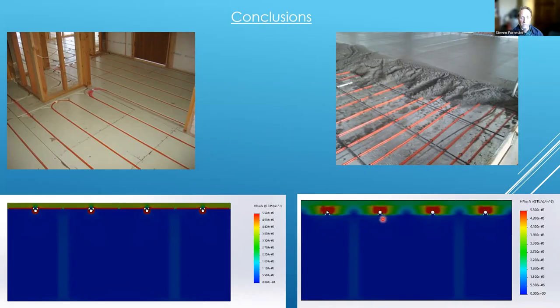So in the Front Range of Colorado here, when the weather changes quickly, in the fall and the spring, with the high mass system, you can overheat the room fairly easily if you don't have outdoor air resets or all those other things going on within the system. The low mass system is going to be able to change temperature faster than you can get with the high mass system. So performance-wise, these are the big differences between a high mass system and a low mass system.